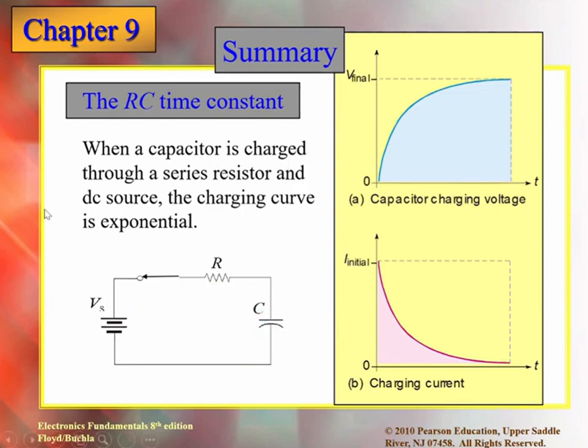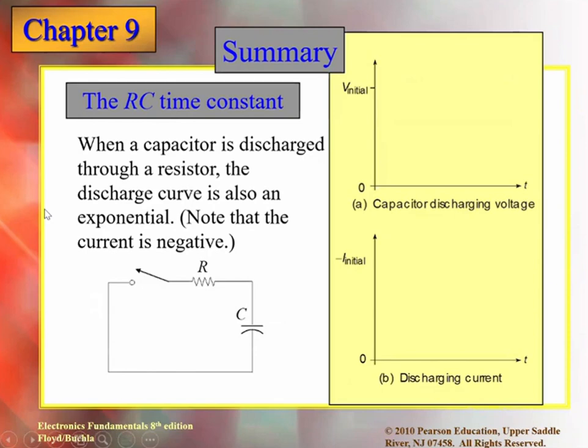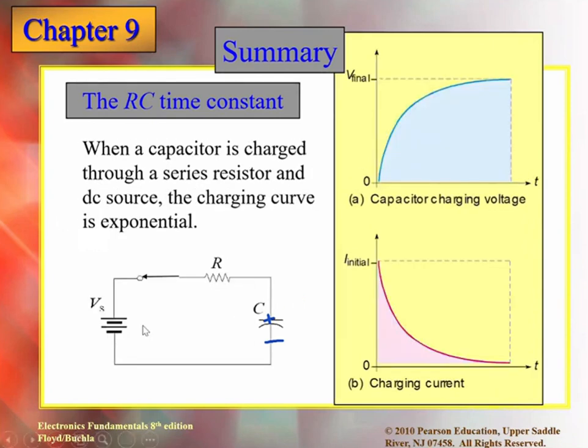So see now, what is the RC time constant? Now we know that the capacitor is fully charged, and I already told you that when the capacitor is fully charged, it can behave like a temporary battery. So let's see what we are going to do. We remove the battery from here, and the capacitor is fully charged. This is the positive terminal, this is negative. Now, why is it positive? You go back to the previous slide and you will see. The terminal which is connected to the battery positive is positive. You can see this one. So the upper terminal is positive, and the lower is negative because it is connected to the negative.